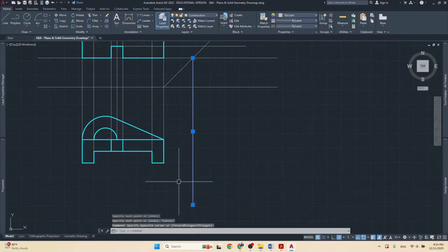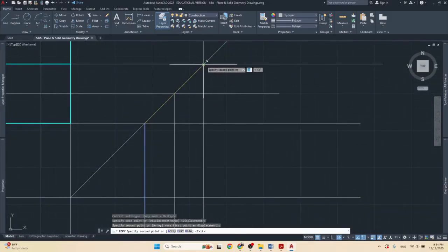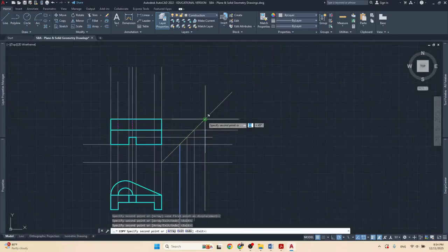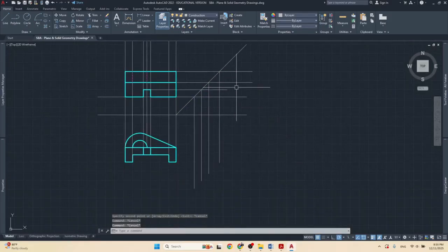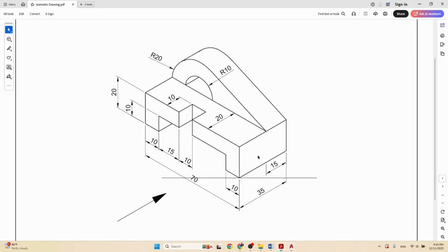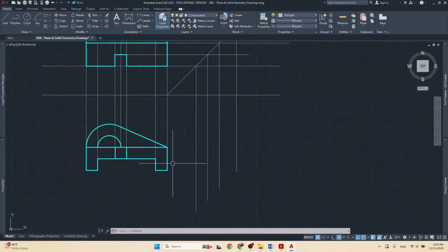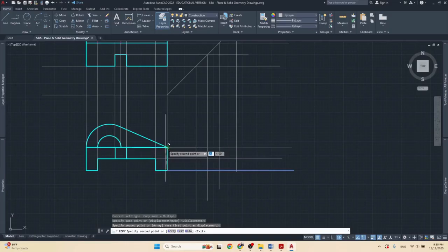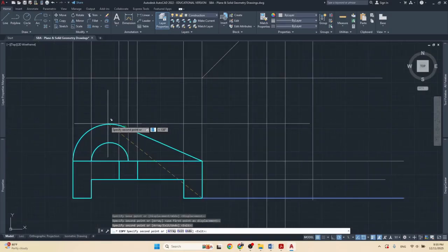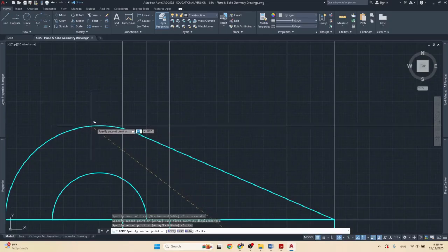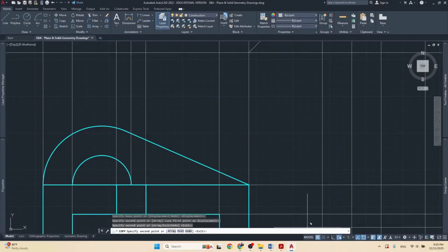So I pull down one, and then I'm going to copy this, just to make it a little faster, put one here, put one here, these projection lines like so. So this is going to help me to draw my right side of my object on the right side of the drawing. Okay, so now we need to project some lines across from all the edges. Let me copy this one and place one here, here, and also at the top, somewhere up there.